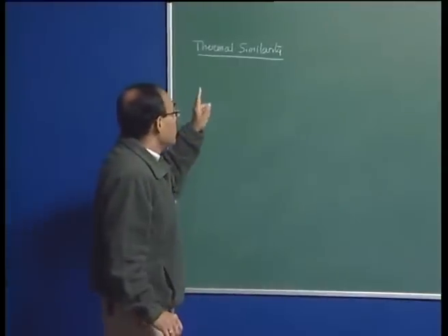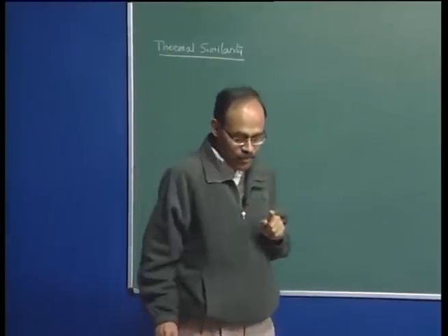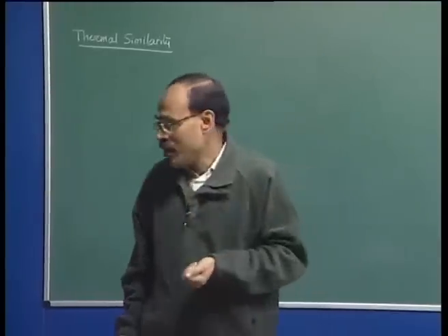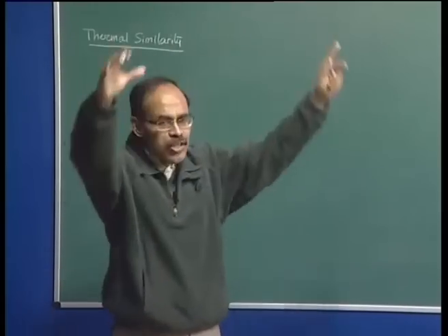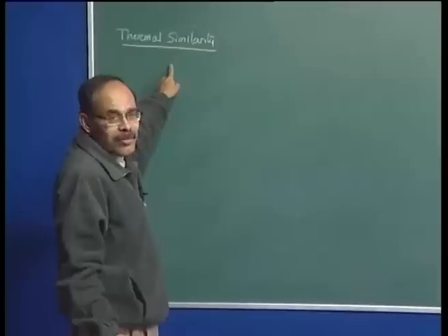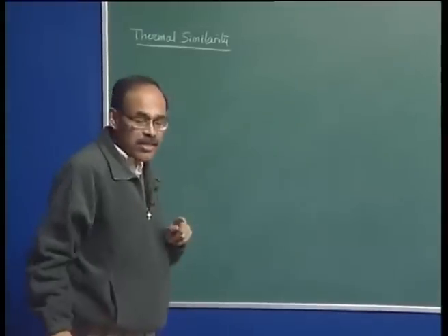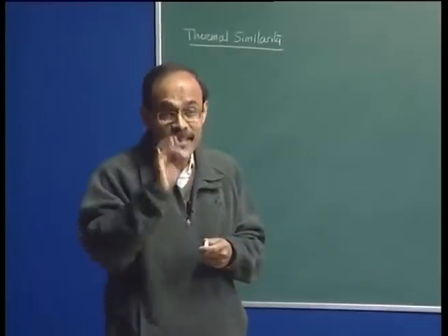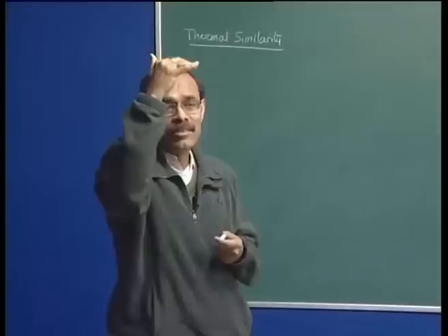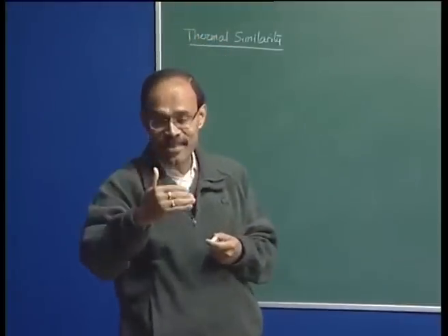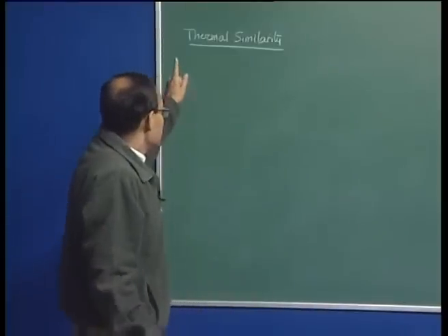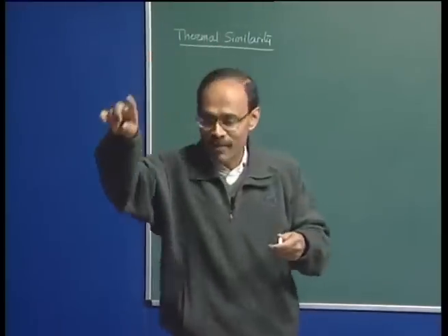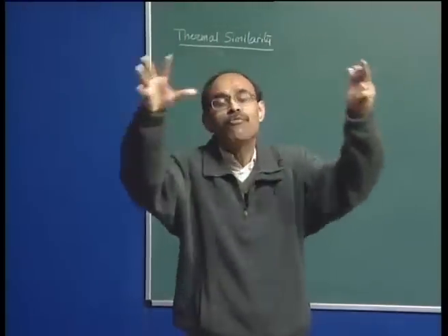Now, before we can satisfy thermal similarity, we must understand that we have to address mechanical similarity or dynamic similarity. Unless we can talk about the similarities of fluid motion in the system, we cannot talk about thermal similarities. That is why when I started talking first about modeling and measurements and outlined the 4 states of similarity, I did mention that the orders are very important. Geometric similarity, then dynamic similarity, then thermal similarity, because if you do not address dynamic similarity, in that case we will not be having similarities of the flow patterns or similarity of flows in the system.